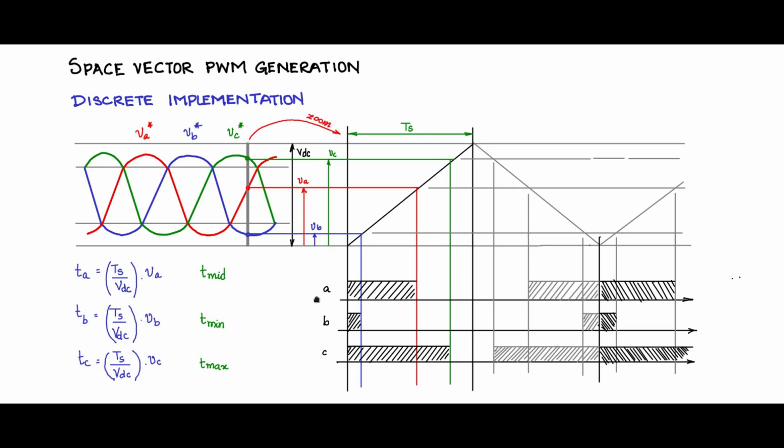So this way we can implement the space vector PWM. This in fact would be the analog implementation. Just compare and then pass it through a comparator. But in the digital domain, we need to give values, numbers, to a compare register, and it will compare with this counter or timer and then make a port high or low depending upon the compare value. So how to calculate and give? We have calculated TA, TB, TC, but observe that,